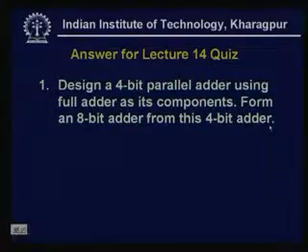When we drew the full adder, we used AND and OR as the digital elements. Now, as if the full adder is one module, first design a 4-bit parallel adder from full adders as the components, then form an 8-bit adder from this 4-bit adder.